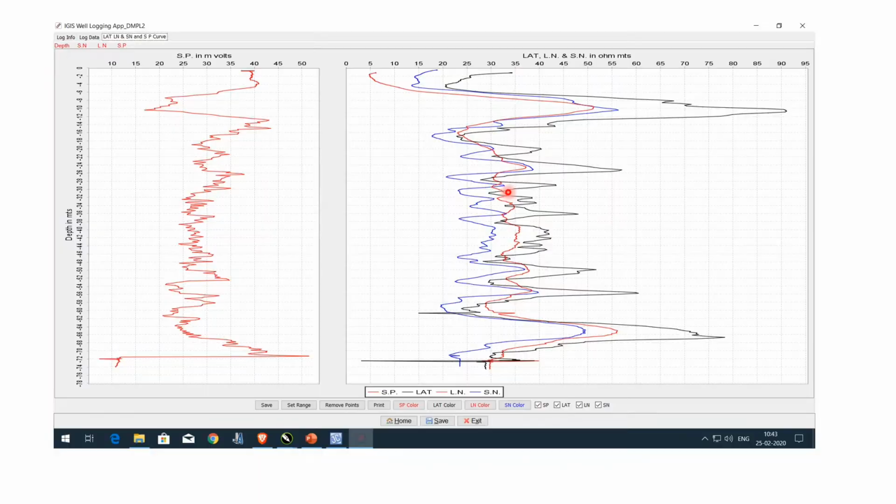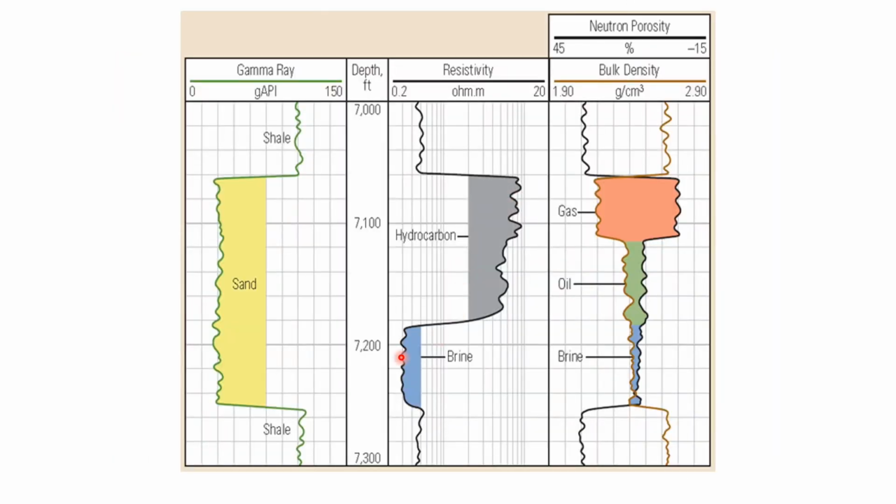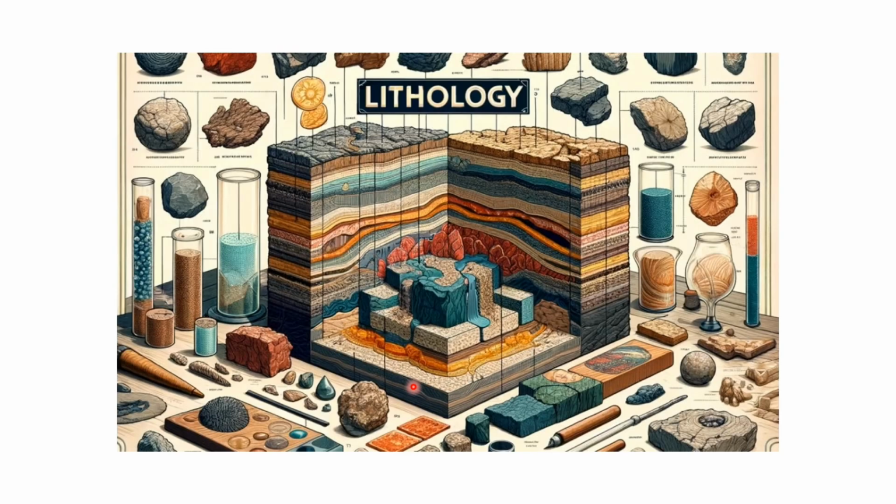So see here, if we have the brine and it is salt water, you have some range in resistivity. The fluid resistivity information depends on the conductivity of the fluid in the borehole and the rock. Then only we can interpret the log. Fluid resistivity information can also be used to calculate the fluid density for the correction of the water level data.